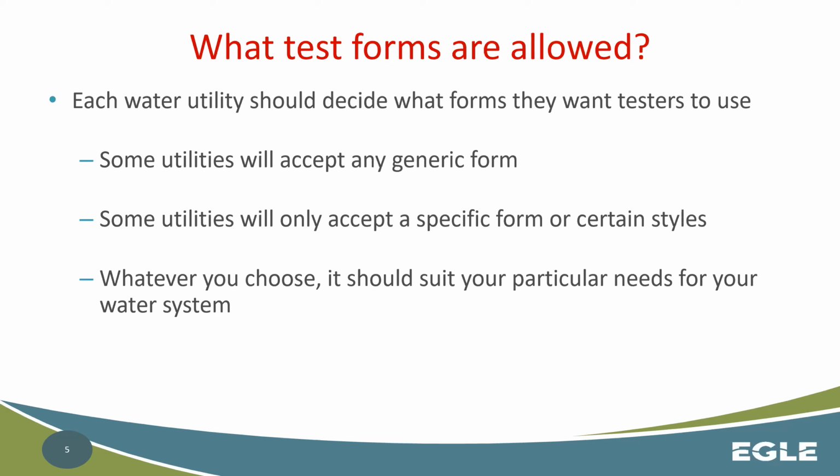Another thing that sometimes you should be looking at is after these things have been tested, there's supposed to be a tested date tag attached to the assembly. You should maybe spot check to make sure that the form matches the tag. Make sure the tag is even there on the assembly itself, because that tag gives someone the idea or the trail, quote unquote, of the paperwork, meaning I could look at the tag, see it gives me a code. I could go to the city, and you should have that paperwork. That's where you need to maintain that stuff.